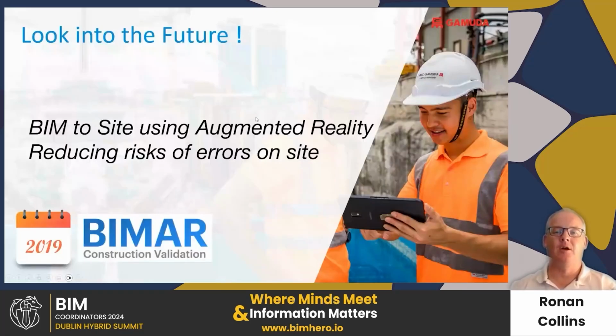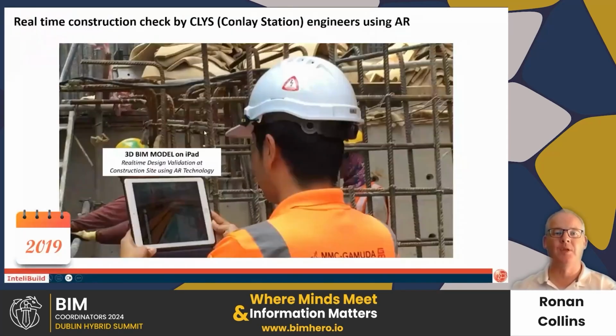So back in 2019, augmented reality for construction was kind of in its infancy. There was a couple of solutions available, but for us, we decided we were going to use our own in-house team to develop a solution. So working with the Gamuda team and between the survey team, the engineering team, and the BIM team, we developed a tool using Unity. So we were able to take information from Revit, bring it across into Unity, and then we had an app that we'd built on the iOS platform, and then we were able to use that app to actually project the models into the job.